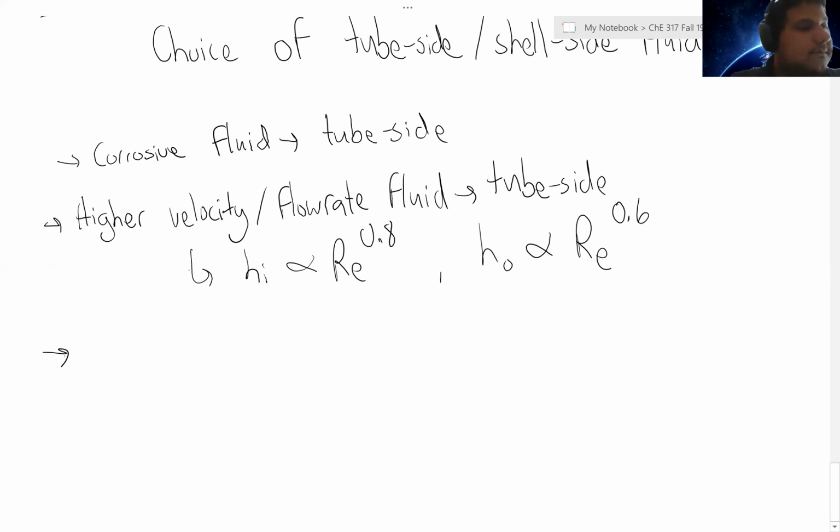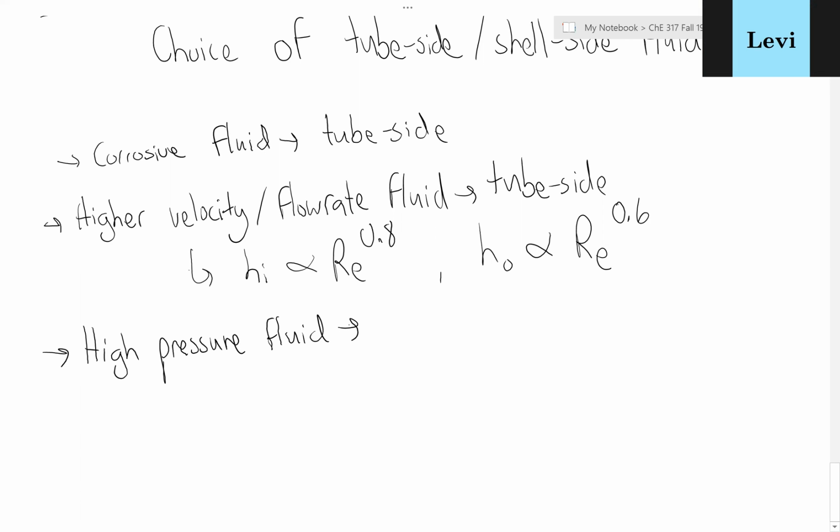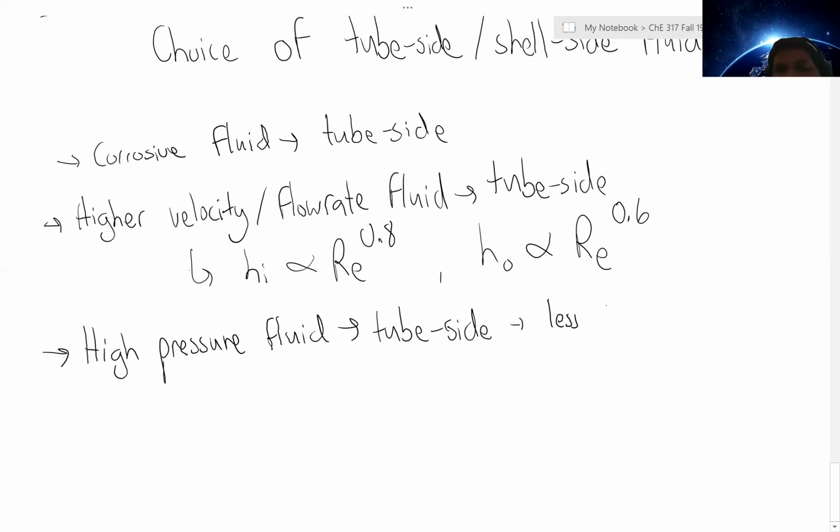What about a fluid that's at a high pressure? Tube side. Why tube side? Because then you only have to reinforce the tubes rather than the shell and tubes. That's true. Keeps costs down. You guys are on point today. Right? Less expensive than a specially designed shell.